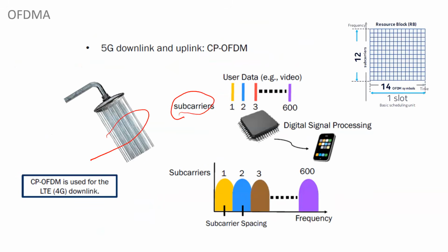By subdividing the channel, small packets can be transmitted in parallel to multiple devices simultaneously, like parallel streams of water from the shower. And by breaking a large block into smaller channels, there is protection against fading. Due to this protection, we get better throughput and efficiency. So the OFDMA method allows data to be delivered to end users through the use of multiple subcarriers.